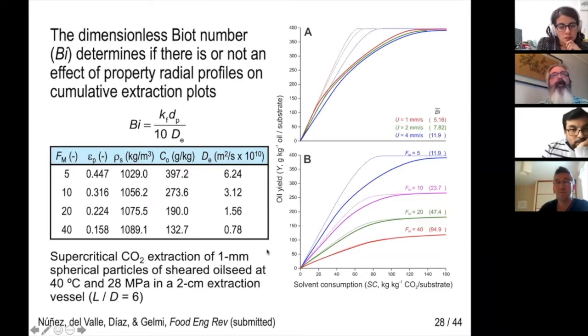Pressing out more oil in sample pretreatment reduced the internal void fraction of the substrate. The associated increase in the microstructural factor Fm from 5 to 40 achieved the required reduction in effective diffusivity. Overall, the distance between the curves, considering and neglecting the radial variations in superficial velocity, decreases as the Biot number increases from 5 to 95, being negligible at the last level.